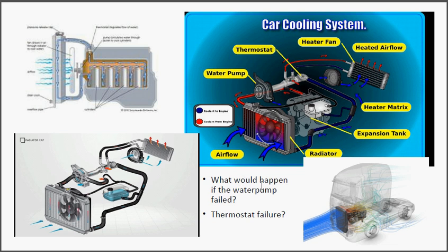Couple of questions I've got here, and let me just ask them to you. What would happen if the water pump failed? Okay, let me just wait for a moment and then let you think about this. What would happen if the water pump failed? You can see this here. We've got a water pump. The water pump is used for convection, so it's forcing water through the cooling system. What would happen if it failed? It just doesn't turn around anymore. Okay, I'm going to wait.